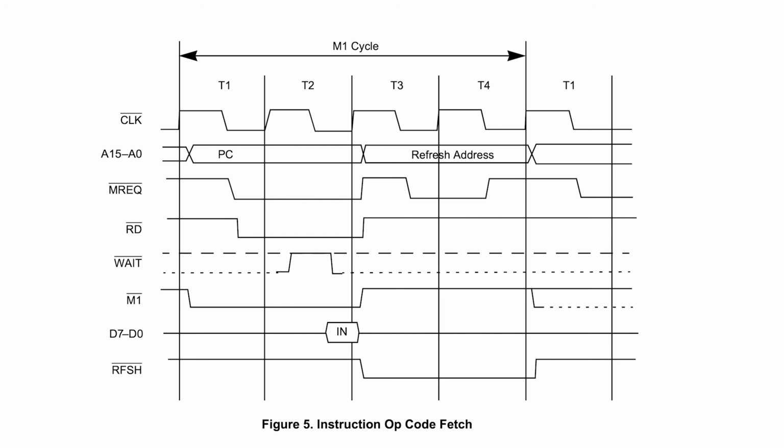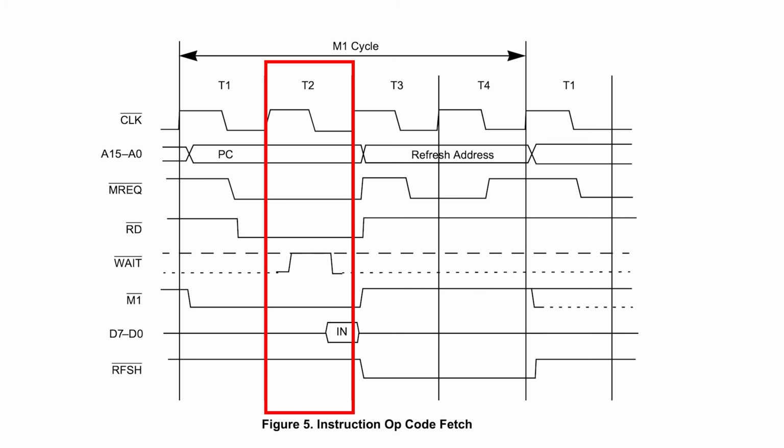The key to this communication is extremely simple. Sending some pre-agreed data pattern on the data bus, specifically the opcode fetch phase, which happens while M1 is active. That's it. If you agree that the byte to trigger the device is going to be, for example, C9, whenever the CPU fetches the next opcode and it's C9, the device can do its thing knowing, hey, they're talking to me.